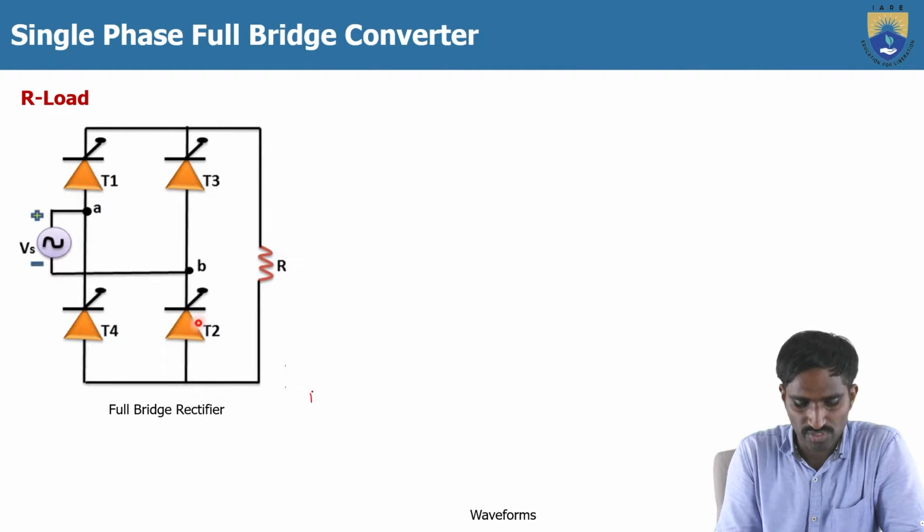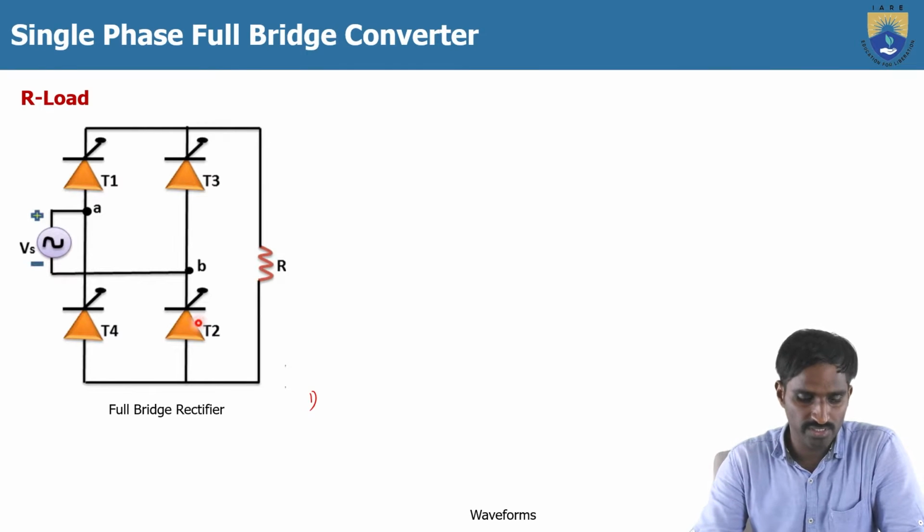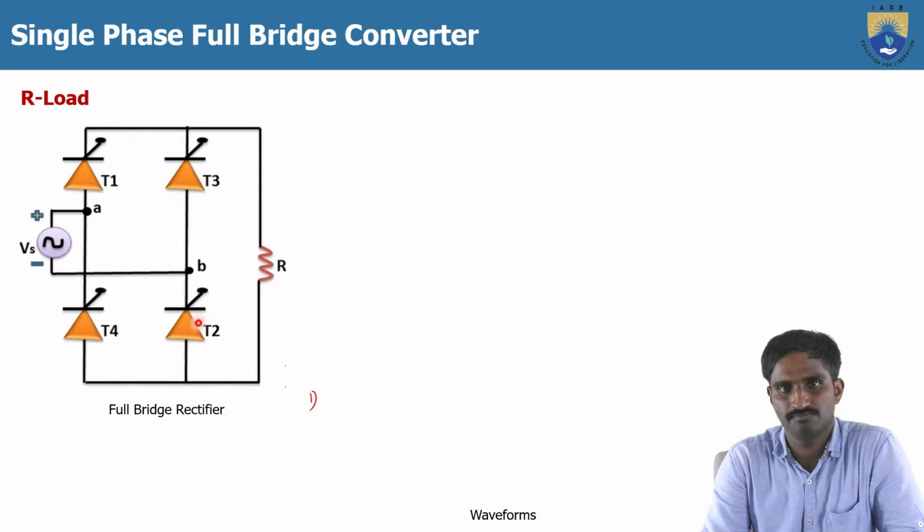The first condition is that the two thyristors in the same leg should not turn on at the same time.